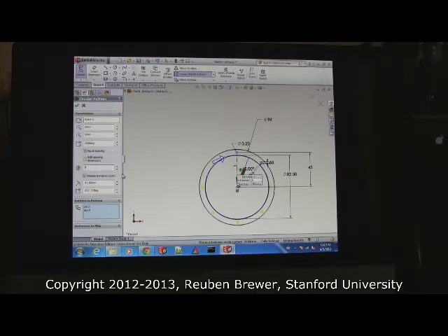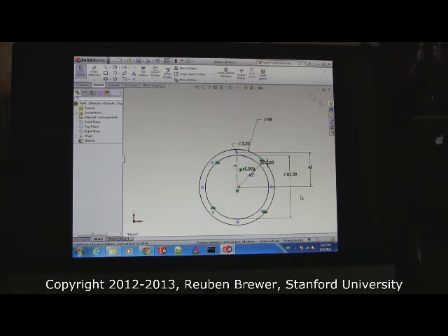Think of this as Legos. We want like 4 types of actions we do, and then we want to do them a billion times. We don't want advanced macros or functions in SolidWorks. It will bite you. So the only thing you're going to do here, just make sure equal spacing is clicked. Hit the number 4 here, and press the little OK check mark. And magically, we have a bunch of holes.